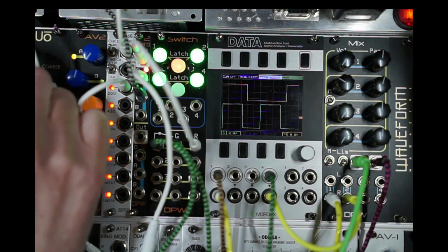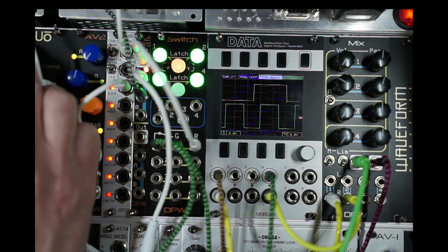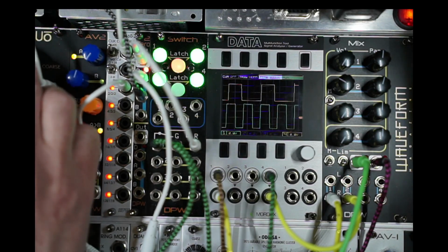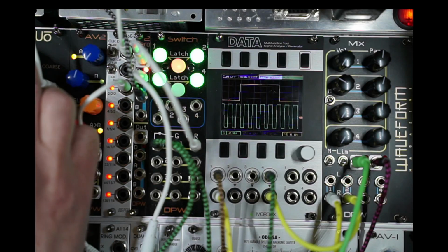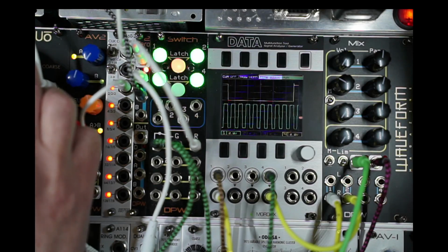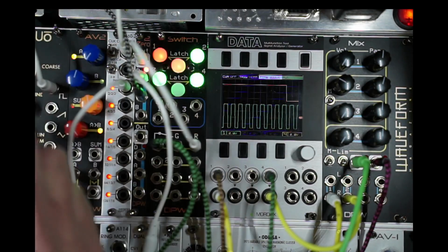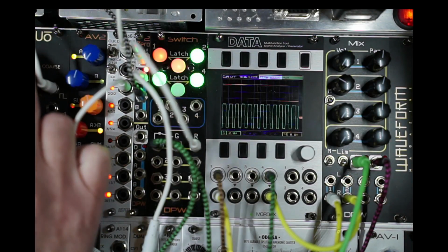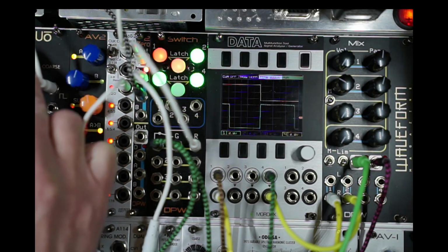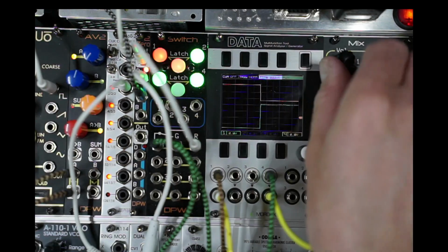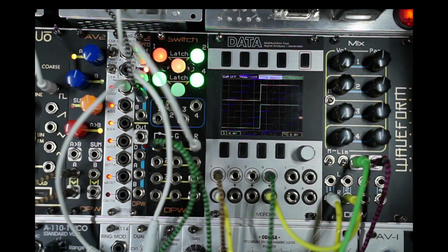What's happening is we will do this not cleaned. So you can hear the frequency is actually going down. And even if I try to clean this up, it doesn't really work. So what's happening there is if you go too high up in frequency, the reclocking won't work because the frequency is so high, so the jitter becomes too big.